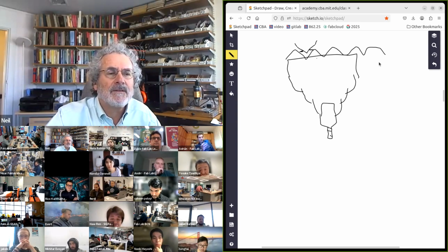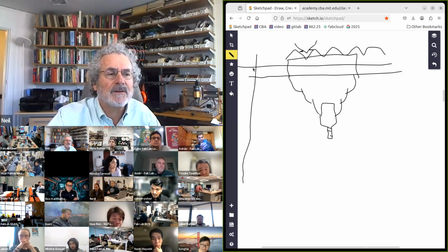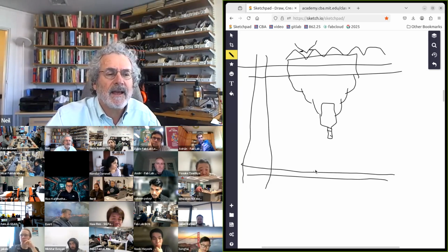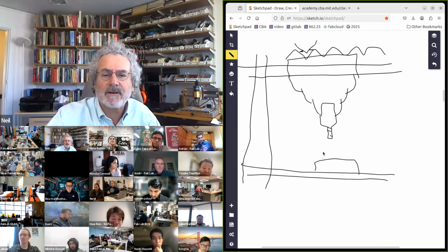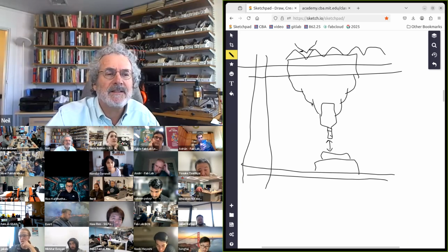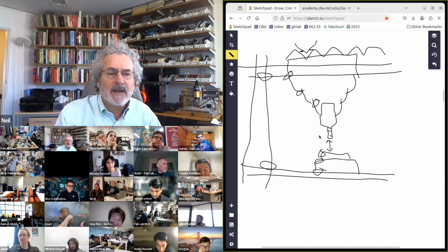And then all of that goes on a horizontal stage that goes onto a vertical stage. And then we have a bed, and then we have our stock, and we have our fixturing. And the positioning between here and here, which is what we care about, actually is a function of the error stack up at all of these positions.